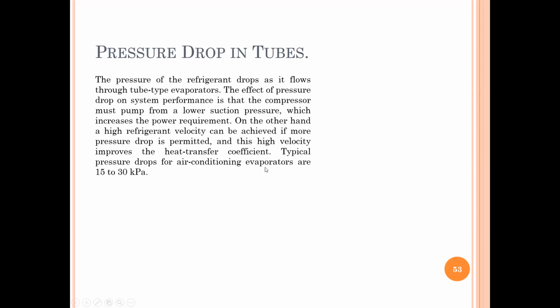So when you estimate the piping, you can average this or maximize it so you get the right pump. Or the refrigerant pressure drop depends on the pipe size. And in the Carrier handbook, there is a pressure drop computation.